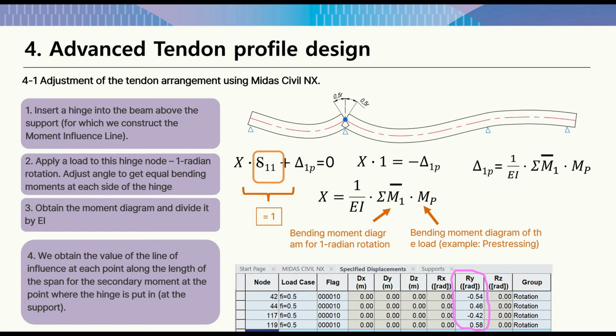And then you just need to draw a line between the secondary bending moment at pier 2 to the secondary bending moment at pier 3, and you will get a bending moment diagram of the parasitic pre-stressing effect for your continuous beam. I'll show you my Excel file.